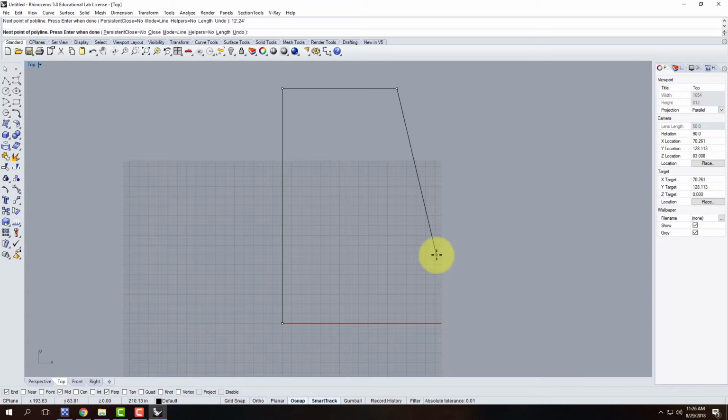The same principles are valid in AutoCAD. Relative coordinates are essentially relative to the last point that I just clicked: where do I want to go? In this instance, the last point that I created was right there. Relative to that point, if I wanted to go down 6 feet, I would use the @ symbol, like the email @ symbol, which tells it it's a relative coordinate.